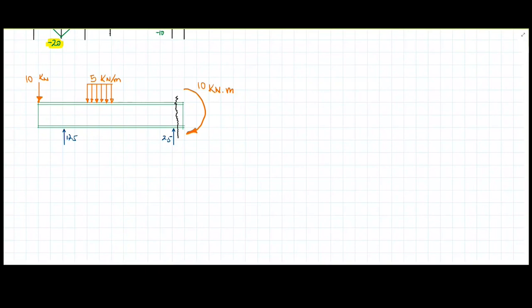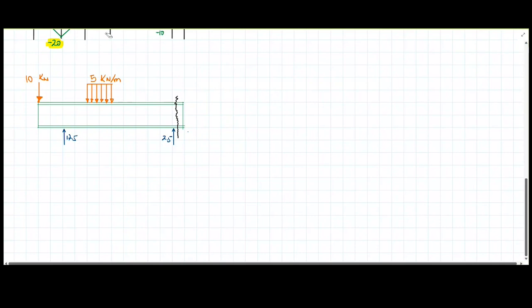So I'm going to make a cut in the beam here, and that means that I'm not going to consider this moment here, neither this moment here. And I'm going to put it a little bit better here. So I'm going to just get rid of this part of the beam, so we know that this is a section XX where we make the cut. Do you have any questions at the moment?